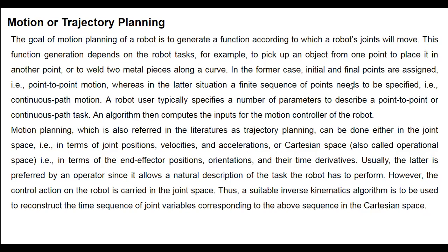Usually the latter is preferred by an operator since it allows a natural description of the task the robot has to perform. However, the control action on the robot is carried out in the joint space. Thus, a suitable inverse kinematics algorithm is to be used to reconstruct the time sequence of joint variables corresponding to the above sequence in the Cartesian space.